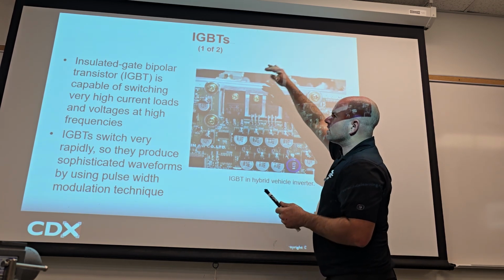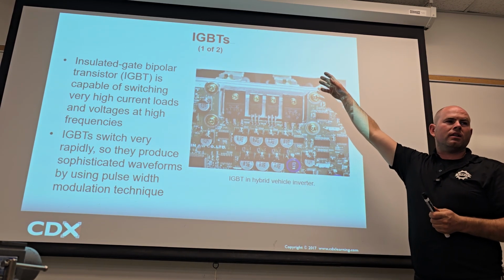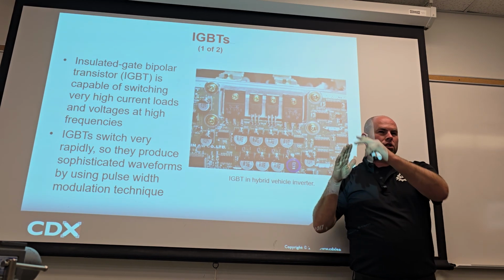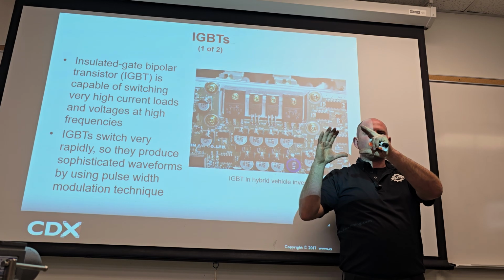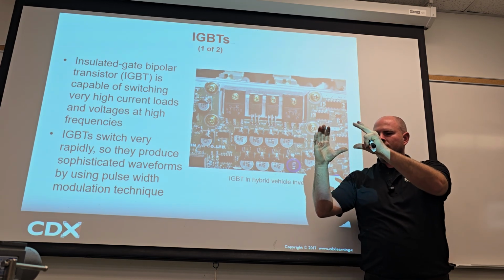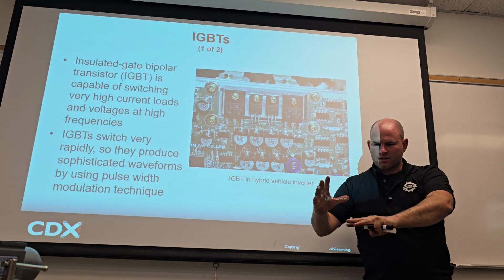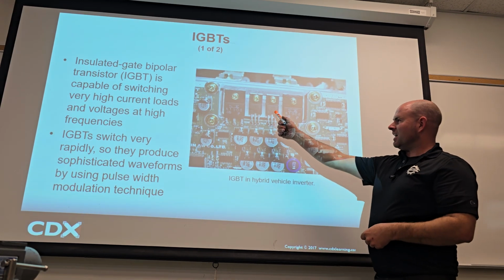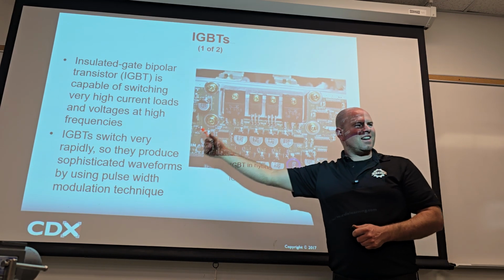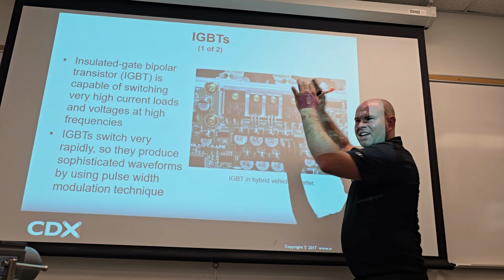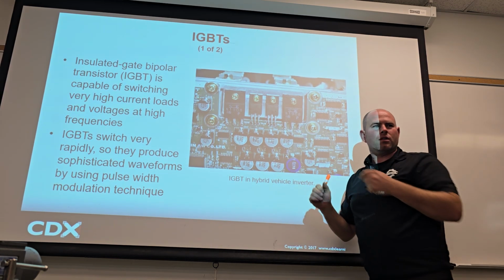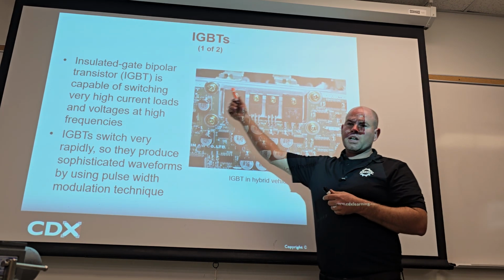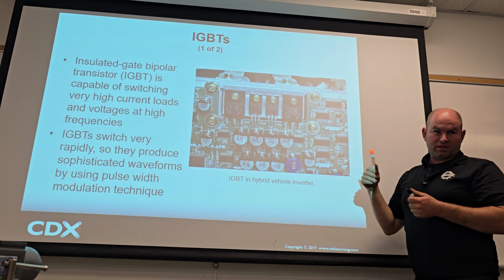And if along the way it has you do some specific tests, they're never going to be this zoomed in. They're going to be outside, because you're trying to determine, in a hybrid, is it the motor/generator? It's one part that can do motor or generate, right? So it's the motor generator, it's the wires, or it's the inverter. If it's in there, it's the inverter. Make sense? What you don't want to do is sell this whole entire inverter, because it's $4,000.